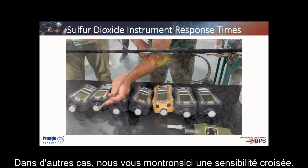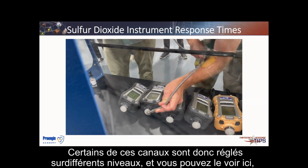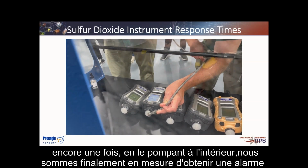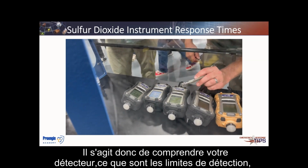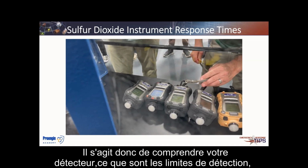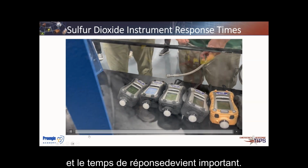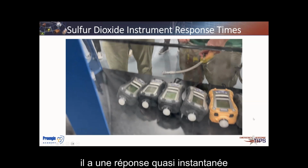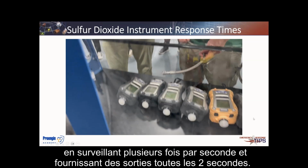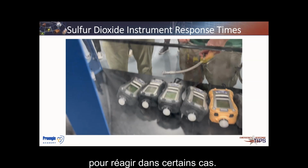In other cases, we're showing you some cross-sensitivity here. Some of these channels are set to different levels, and by pumping it in there, we're eventually able to get an alarm on those cells. So it's about understanding your detector, its limits of detection, and that response time becomes important. AP4C, because we're working on light, has some advantages because that's almost an instantaneous response. We're monitoring multiple times a second, giving you the output every 2 seconds. Electrochemical cells just take a little bit longer in some cases to respond. Next slide, please.